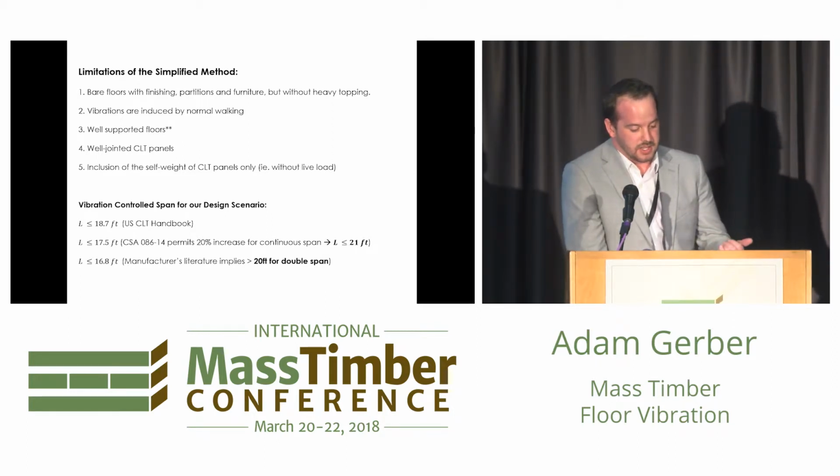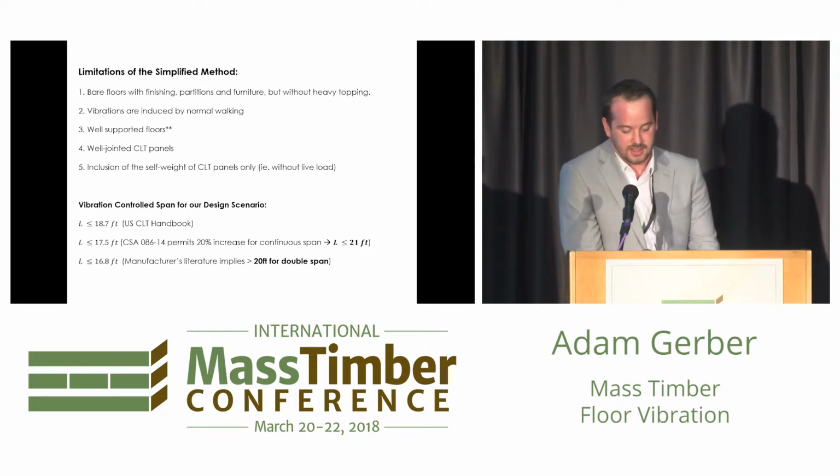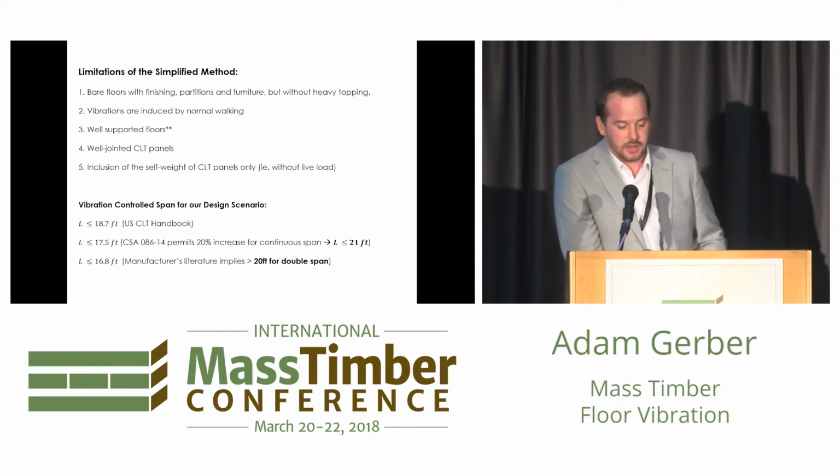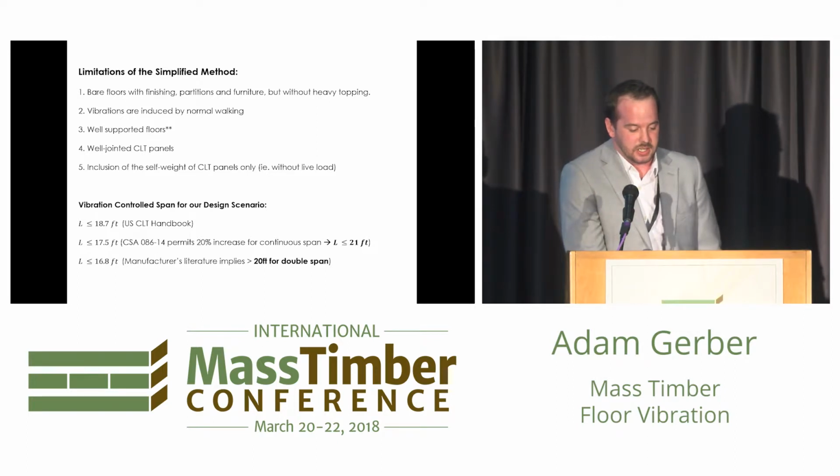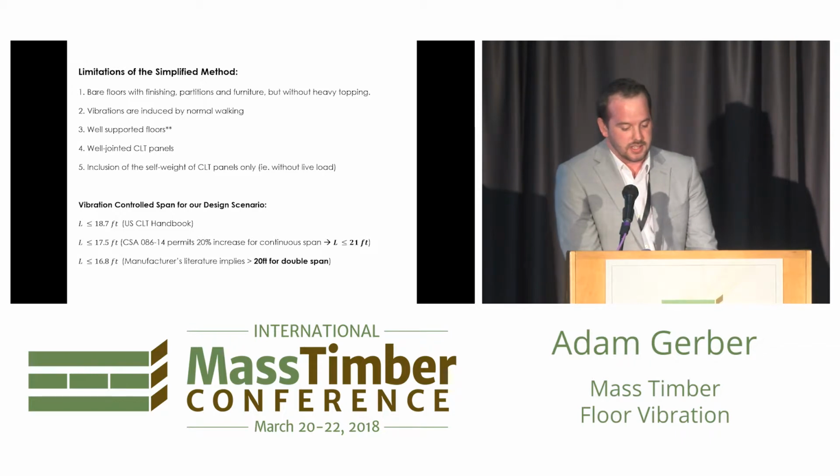If we use this procedure, we get a few different results, but they're all generally telling us the same thing. From the US CLT handbook, we get about 19 feet. From the Canadian code, we get about 21 feet. And from the manufacturer's literature, it's saying about 20 feet is the vibration governed span. So I think at this point, considering we're spanning onto walls and we do meet the well-supported floor assumption, I think that we've done our due diligence and we probably have a compliant design.